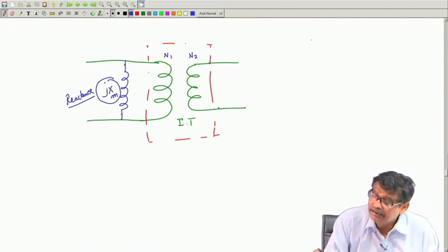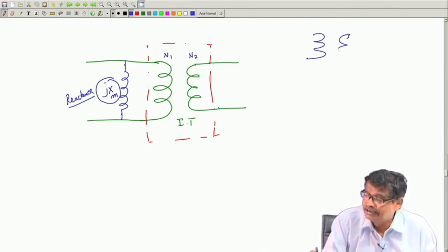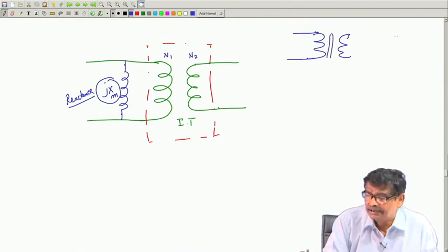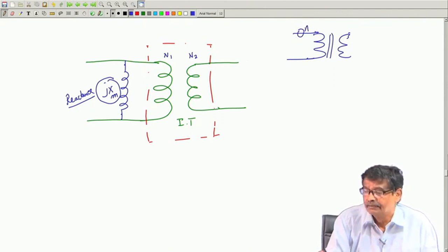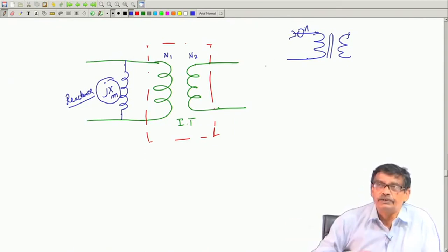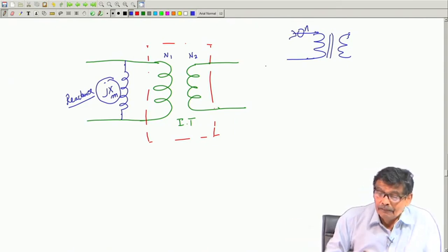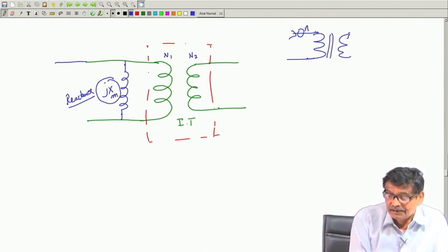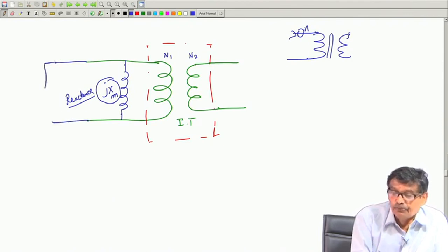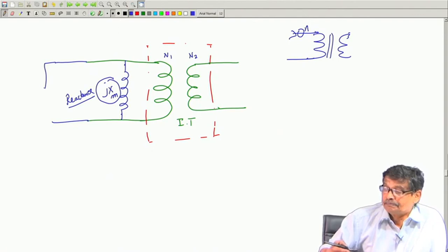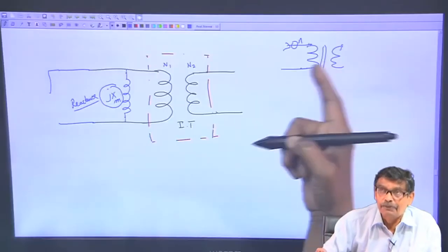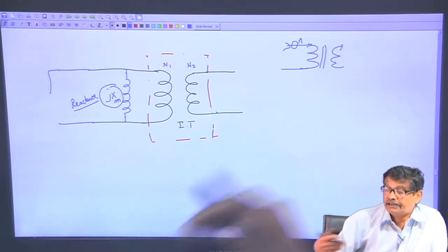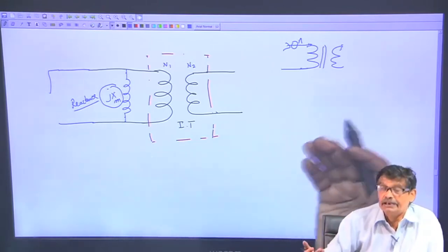That is what I am telling you, that your practical transformer is like this. Here you observe that when nothing is connected, the ammeter shows the magnetizing current. When a load is connected, it will draw a current I1, which is Im plus I2 dashed. That is what we have seen. Let us see whether it can really, faithfully, follow the rules of this practical transformer, and represent whatever is happening in a practical transformer.